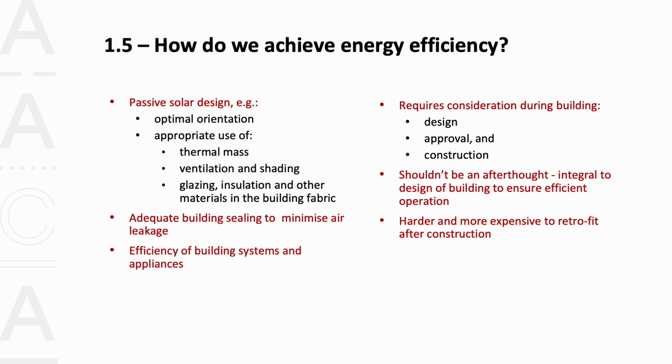Ventilation is another key consideration that's often forgotten. For example, in warmer climates and in summer in most parts of Australia, good ventilation can help clear the heat that builds up during the day and provide a comfortable temperature for sleeping at night. In climate zones that are warm all year round, i.e. climate zones 1 and 2, good ventilation can make a big difference to how much heat builds up inside the building and to the user's perception of the thermal comfort within that building. Shading can also be useful to consider. For example, in cooler climates, positioning the building to avoid overshadowing.